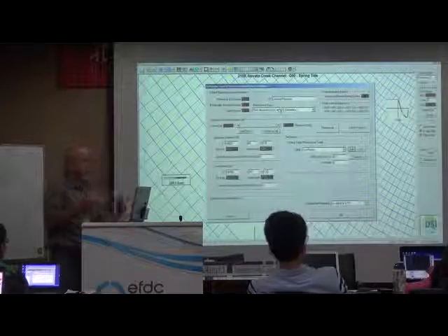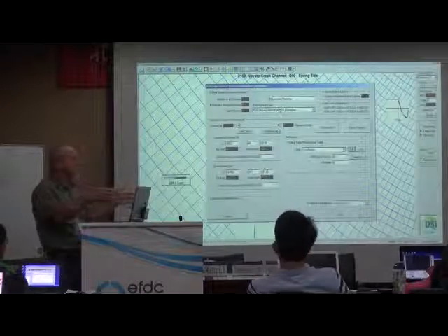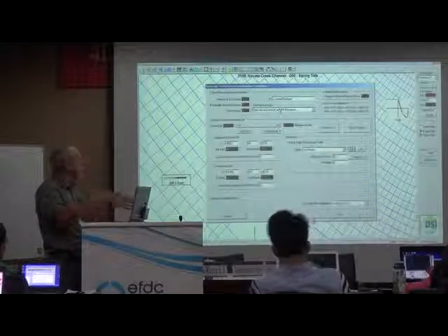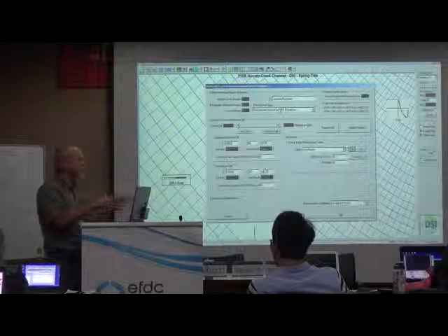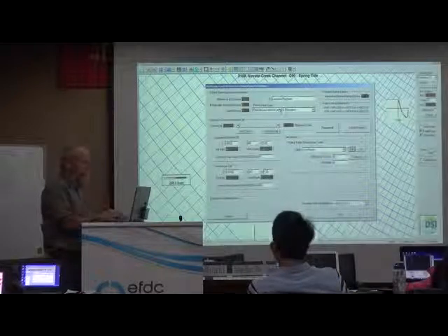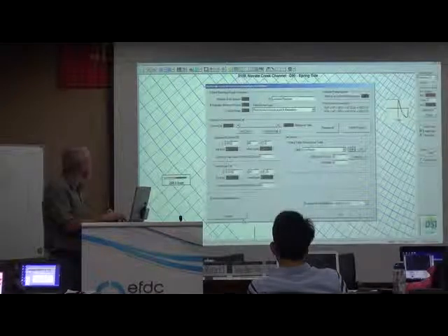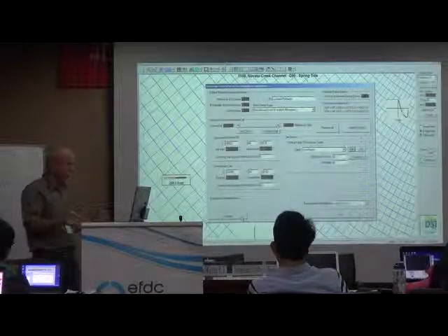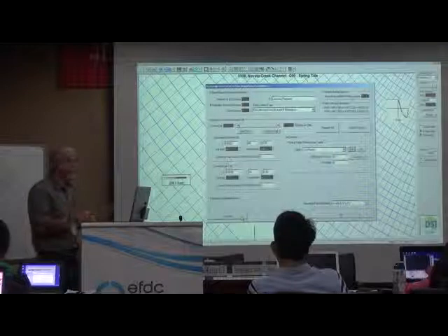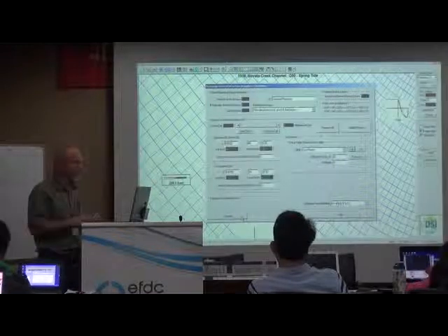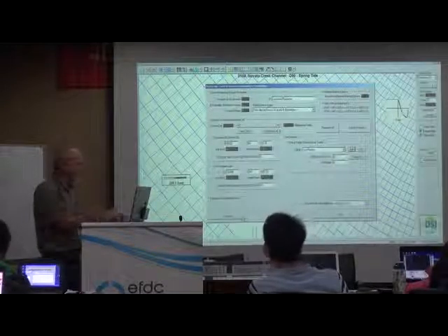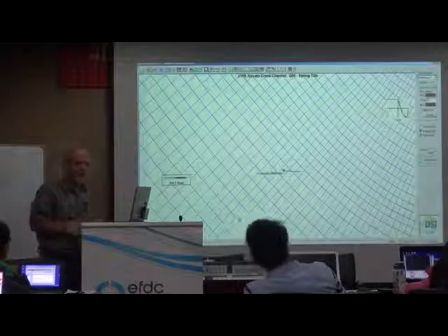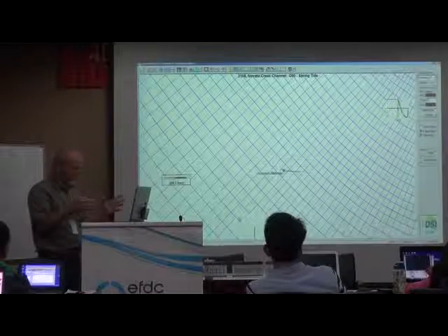So for instance, even if you had a series of pipes underneath a major road, and you knew the hydraulic behavior of those, then you can put that table into EFDC, and then EFDC can handle that structure just fine. Okay. And with that there's a lot of details we can play around with. Time series contours are nice to be able to display. Now I don't have the right model loaded, so. But we have this.